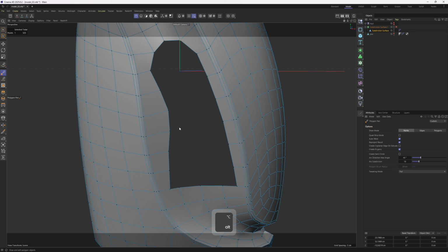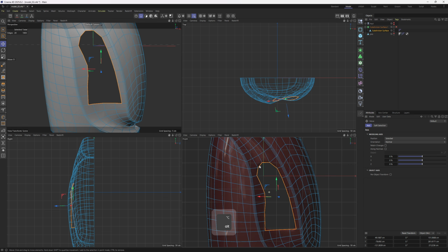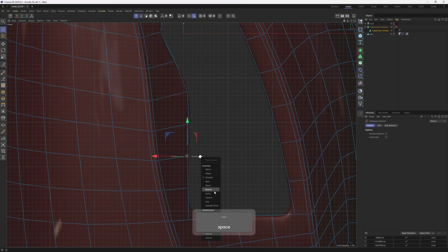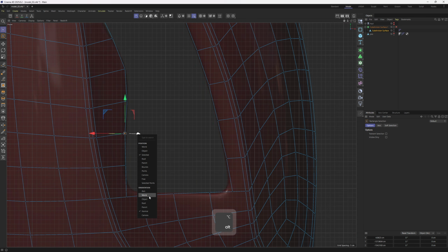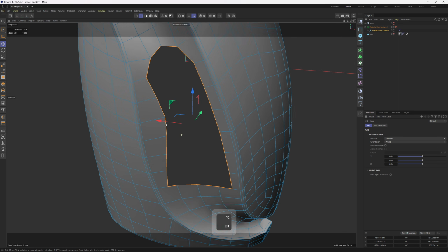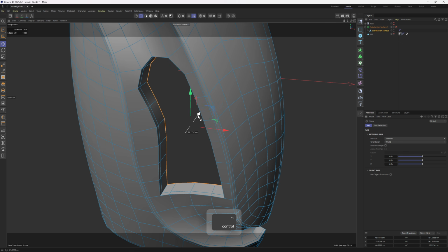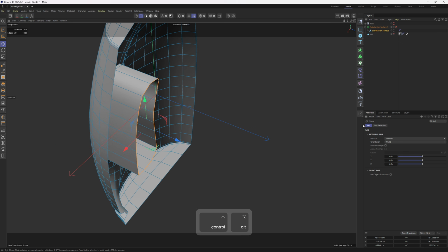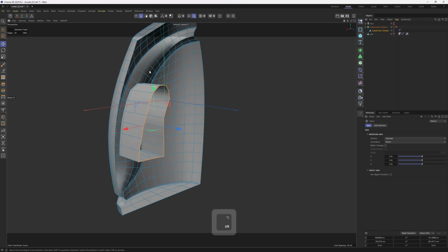That was easy. Now let me double click on the loop. That part is uneven. Let's set this to world. Right click, world. Okay, seems better. I will hold down Control and extrude these edges 2 times. Now, while these edges are selected, I will come over here and zero out the position and the size.